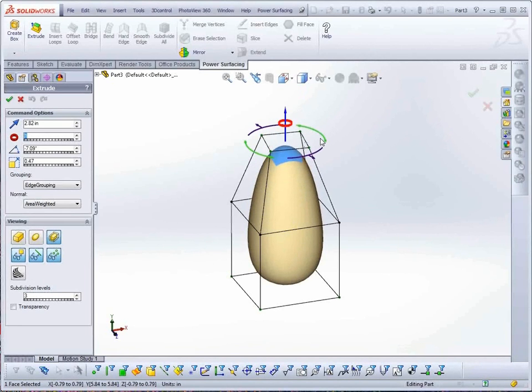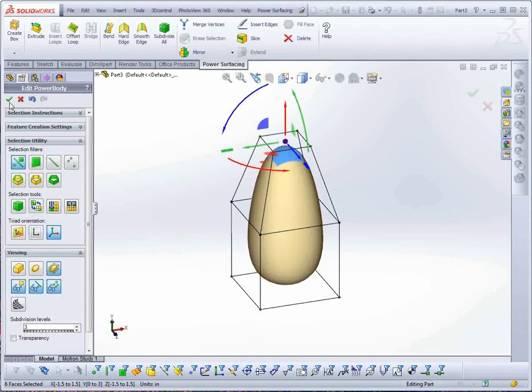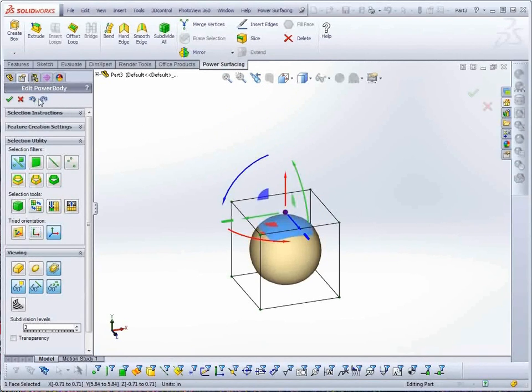You will see these specialty gizmos in several of the other editing tools. To complete the command, right-click, press the familiar green OK checkmark, or press the Escape key. The Transform gizmo, or triad, reappears. If you change your mind, simply press the Undo button, or Ctrl+Z.